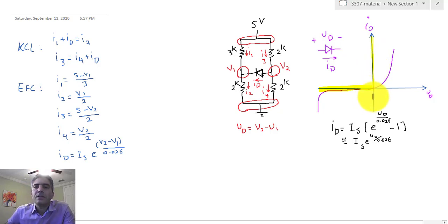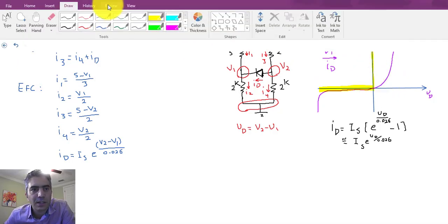In other words, you turn this nonlinear equation to two pieces of linear equation right around 0. These switch from one to the other, and it's basically kind of a switch actually. So it says for any negative voltage, the switch is open, and for any epsilon positive voltage, it becomes a short circuit.